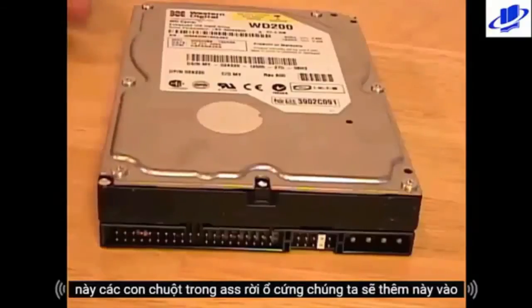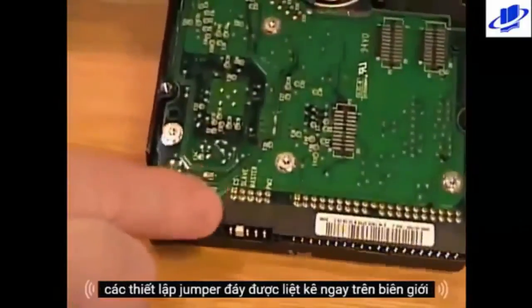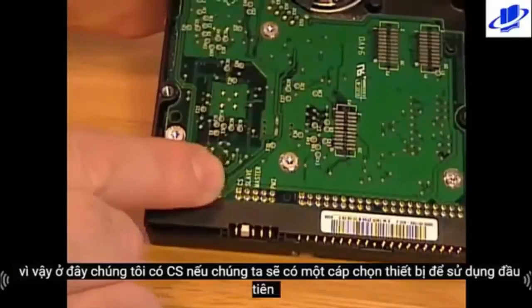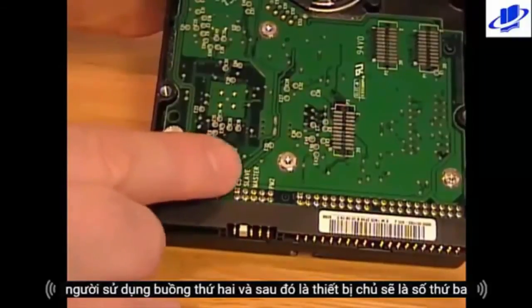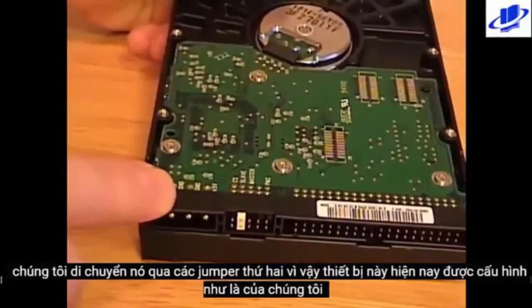This device is going to be our slave hard drive. We're going to add this to the primary controller. This device doesn't happen to have a legend on top, but if I turn it over, the bottom jumper settings are listed right on the board. So here we have CS. If we were going to have a cable select device, we would use the first jumper. If we were going to specify this as a slave device, we would use the second jumper, and then the master device would be the third jumper. In this case, this is going to be our slave device. We will move it over to the second jumper. So this device is now configured as our slave device.